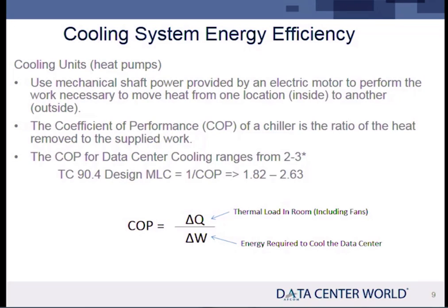It's fairly easy to figure out because you can go to your UPS and see how much load you have going into the room, at least the IT load going into the room. And then hopefully you can also go to your transfer switch and find out how much power is going to the cooling system. It's the ratio of those two numbers, if nothing else, even if it's a spot check on a given day. Pick a hot day and then pick a cold day and see how they vary. Compare the two numbers. It's the ratio of those two numbers that really makes the difference in energy efficiency of your data center. And it's important to know where you stand.